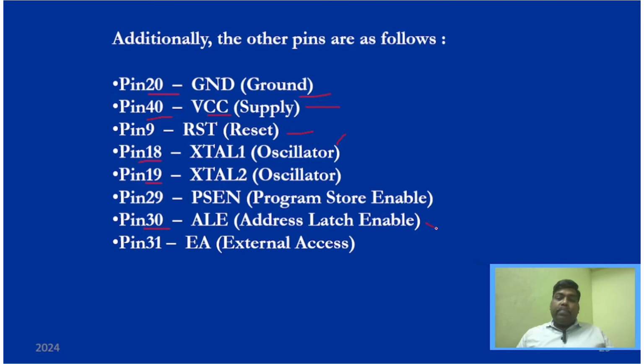This is an interesting pin which is used for demultiplexing the address bus and the data bus, right? And similarly, EA is another pin which is also used to access the external program memory, right? So this is the pin configuration of 8051.